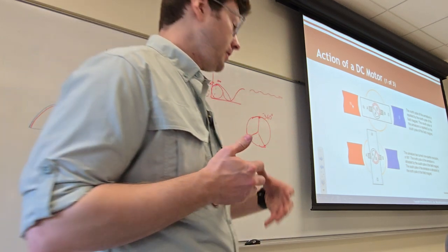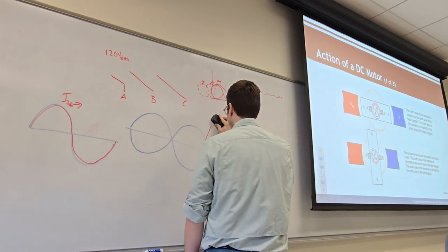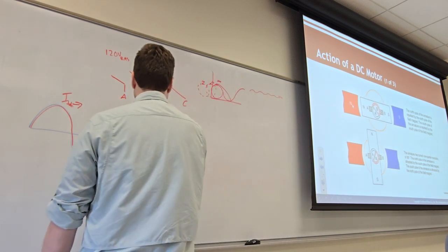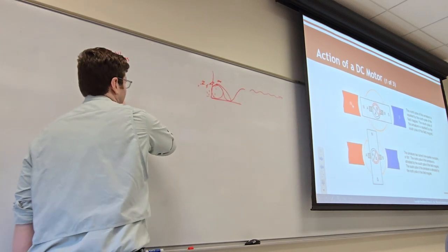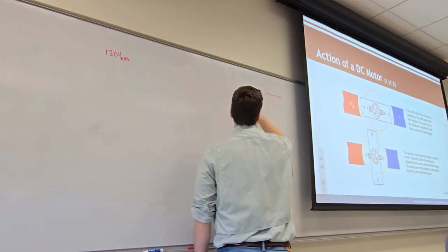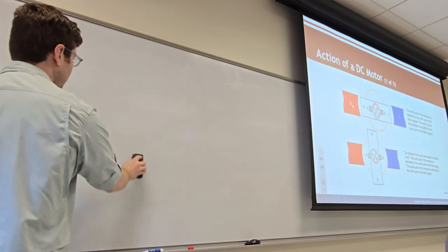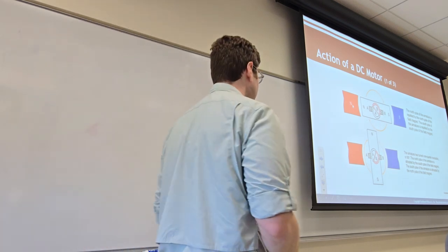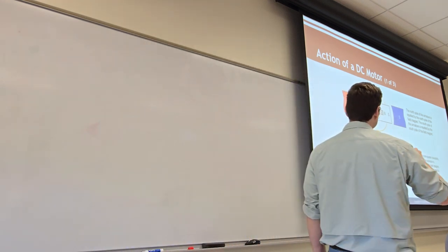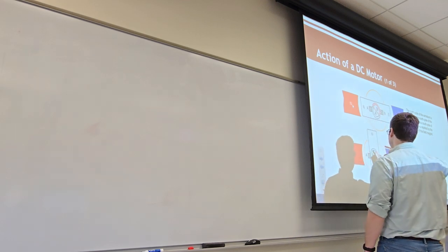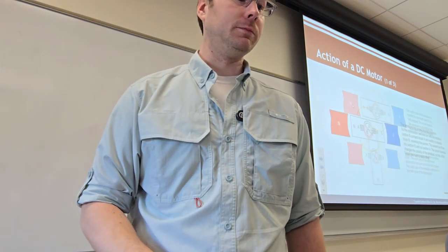All right, so the theory of operation at its most basic is that we really are just getting a magnet to kick over. If we put a magnet in a magnetic field, that magnet will want to turn over to get to the position of least resistance. It'll move until the force on it moves it into the position where it wants to be. But if we were to switch the poles at that resting position, it would want to kick over again into the other 90-degree position until it's dead again, right?